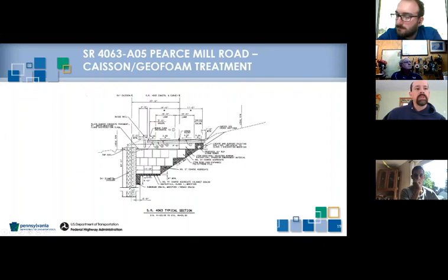As a slope treatment, you can have more deflection and more other things be allowed so that you don't have to have as much reinforcing in your column, and also you're relying on some of that slope to still be there. You assume a few feet down has failed, then you're still getting a buttressing effect towards the lower part.